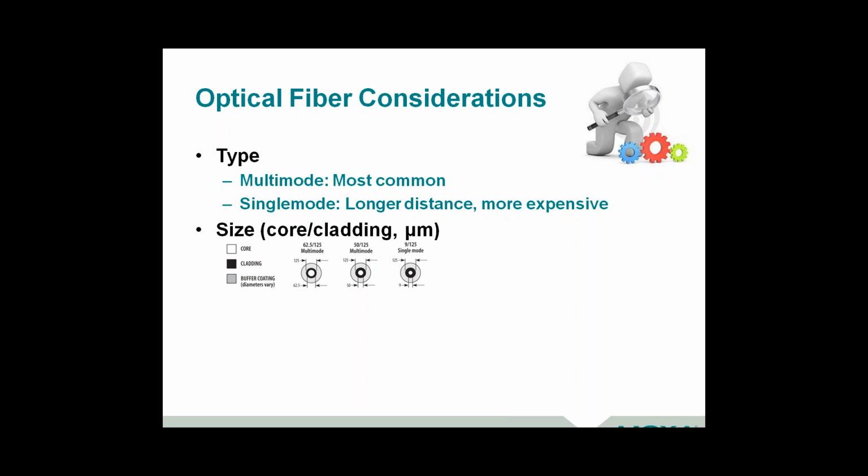So when you're doing this, pay a little attention. Looking at the data sheet for the fiber media converter, it'll probably give you performance specifications for both the 62.5 micron and the 50 micron, and tell you that your distances vary a little bit based on what you want to use. Typically, you'll find the 62.5 is the more common for this.